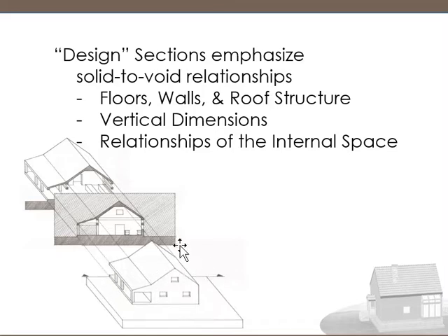Each different location will offer a different viewpoint. So if I cut a house in the front or back, or east-west or cross-wise, every single way I cut that house or structure is going to give me a different viewpoint. That's why we have to be really careful when we do our cuts through a section, that we know exactly what we want to see and what we want to draft. That takes a little skill and a little eye to pay attention to what is going to be interpreted on a multi-view drawing.